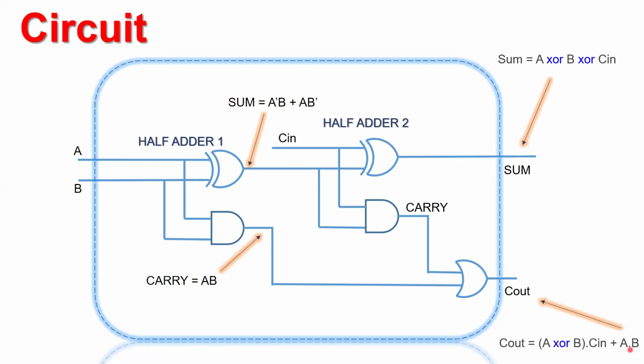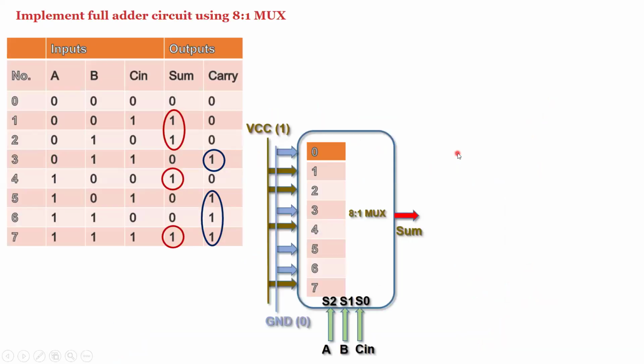If you take an example here, you will see how this circuit will implement the full addition. Just take A and B, let's say 1, 1. Then the sum here is 1. Carry here is 1. The C out is 1 because one of the inputs here is 1. And since the XOR is 1, then C in got generated as 1. So the output is 0 here. Sum is 0 because both inputs are 1. So this is how you can see that the full adder works.